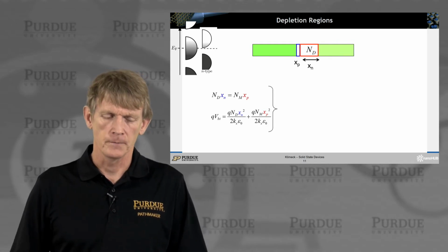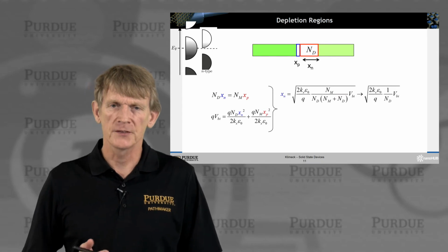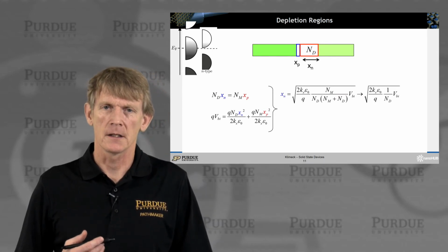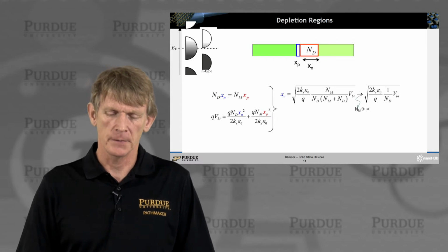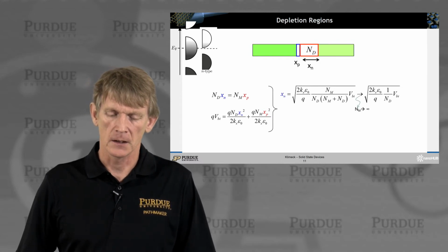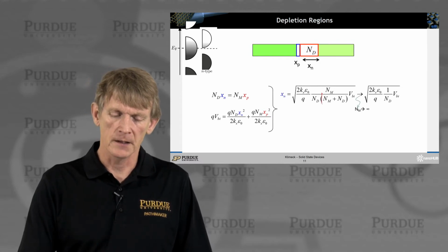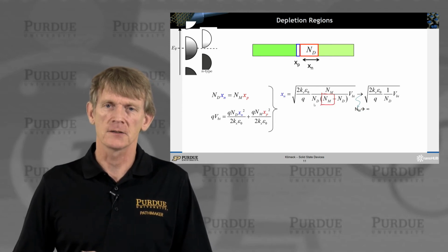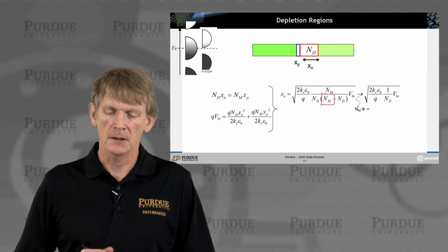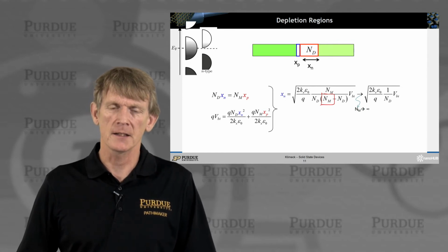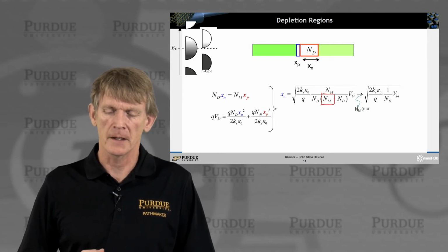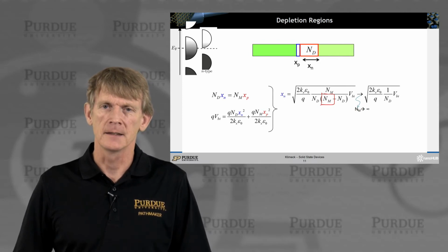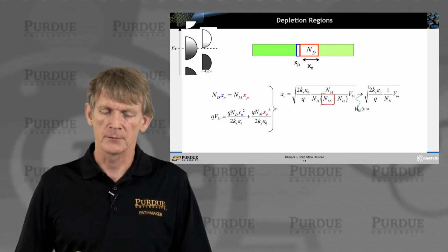Okay, now we can resolve these distances on the N side and also on the metal side. Now we have an expression here where we have the number of states in the denominator. Now, if you can assume that the number of states is much, much larger compared to the doping density that you can provide, then this term drops out.